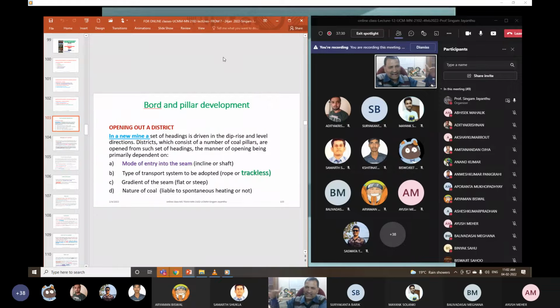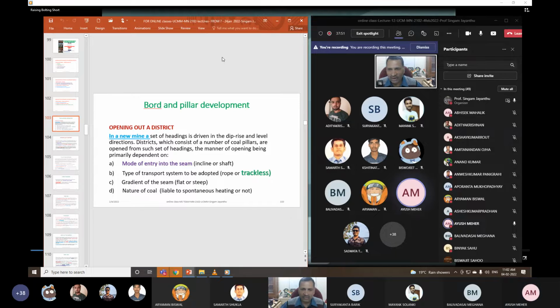You understood. Under shear, only 1/3 of it. And this is a sample strength, but this is not the strength of the rock mass in the field. That may be almost 1/5 to 1/10 again, right? These are the things you should know when we are designing. It will come at that time. Also, I will show you how pillars are designed. Yes, any other doubts?